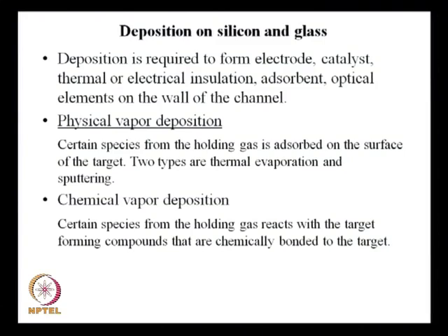After the sample mixes with the reagent and they flow, they undergo passive mixing, then some operation, and then you may be looking into electrical field flow fractionation, where you are basically putting them in bands, in layers, using 2 electrodes. So, an electrode has to be placed on the channel, one anode and one cathode on the wall of the channel. So, how will you deposit this material on the channel?